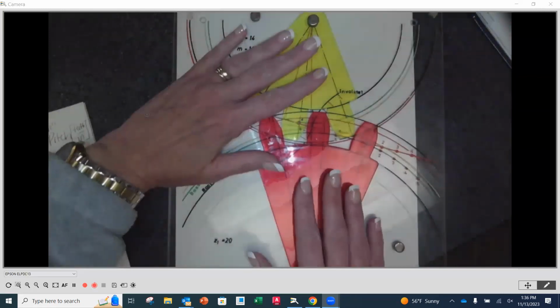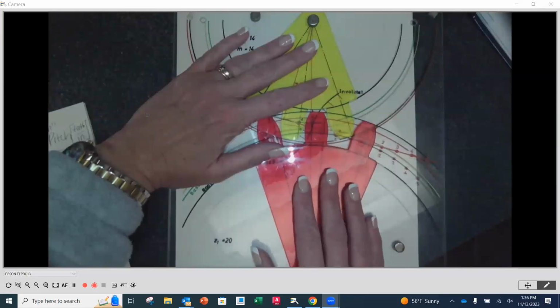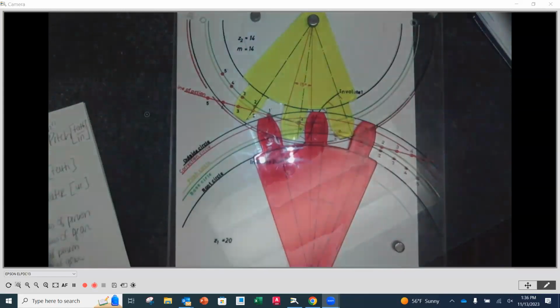Now, some gears like spur gears are going to have more backlash than some other types of gears like the helical and the herringbone. And all that means is if I were to reverse the direction here, I would have a little bit of a gap before I would get re-engaged. Sometimes you can feel this on older knobs and handles that you have to crank on. When you go back the opposite way, you can feel that difference before it engages. That's backlash, and backlash will increase as something is used over time, but we need backlash.